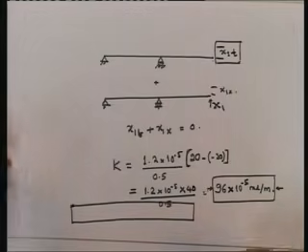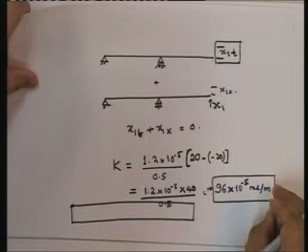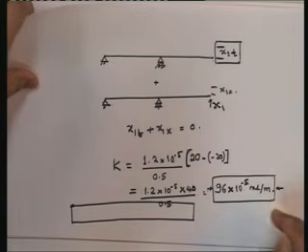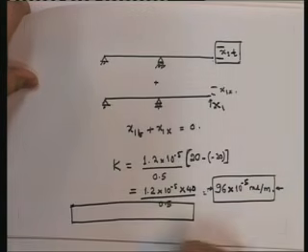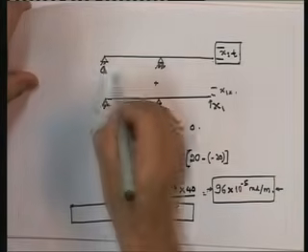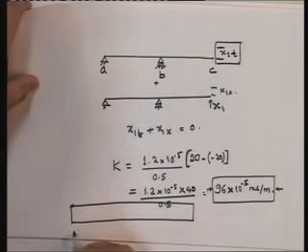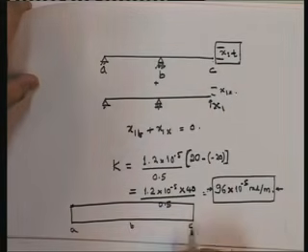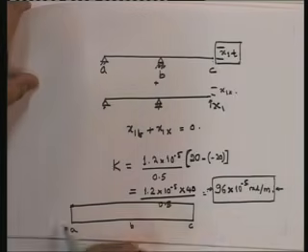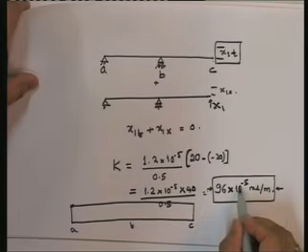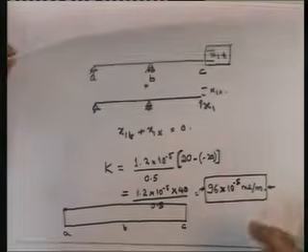Okay, now if I put A, B, C, due to the temperature, I have a constant flexure across the entire beam of 96 into 10 to the power of minus 5 radians per meter.